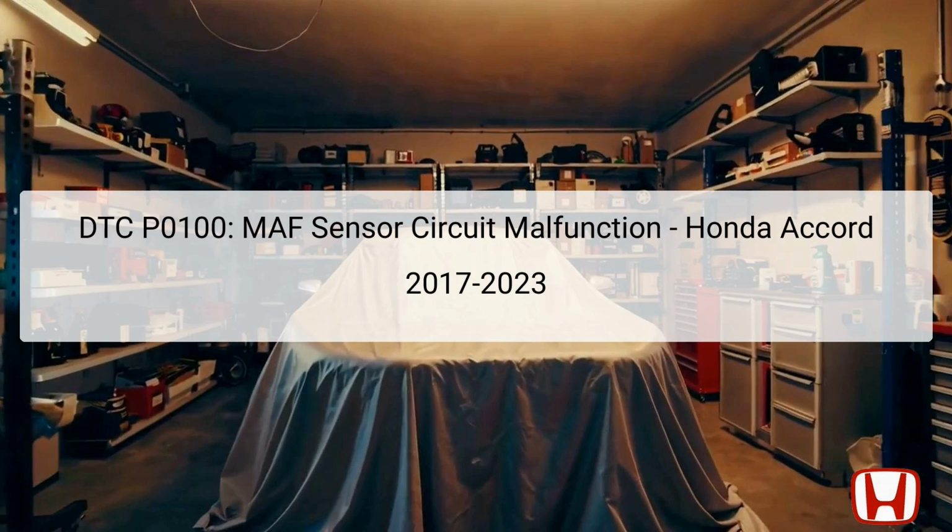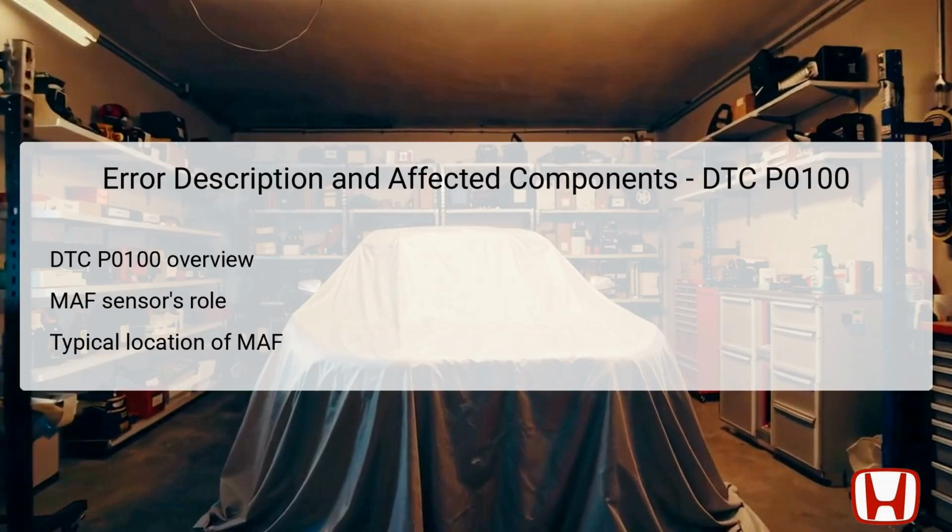relevant to DTC P0100. DTC P0100 points to a malfunction within the MAF sensor circuit, which is crucial in measuring airflow into the engine. The MAF sensor, or mass airflow sensor, calculates the amount of air entering the intake manifold, enabling the engine control unit, ECU, to adjust fuel injection accordingly for efficient combustion. This ensures optimal engine performance and emission control.